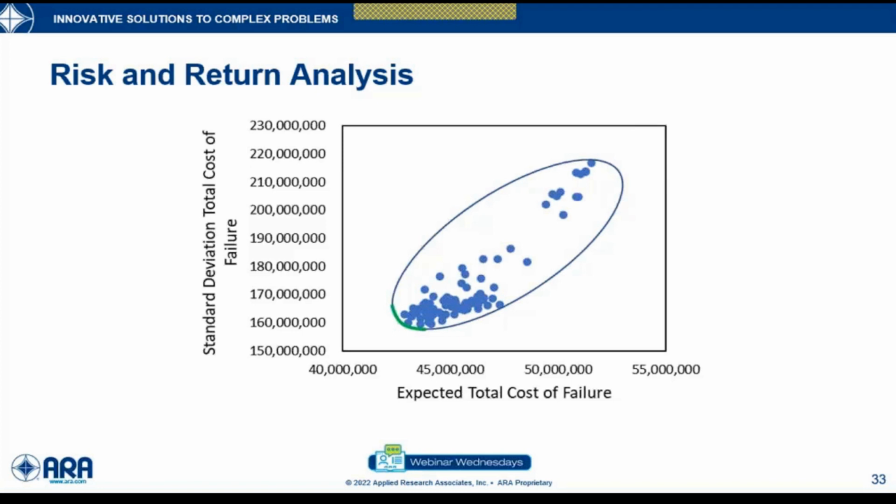The other thing to ask when we were talking about risk is basically the frequency of that event to occur. And the frequency in terms of probability, or basically, again, at the individual level, the probability of failure, or the frequency at the network level. So these are some of the basically major questions to ask. But when we're talking about risk-based data collection, focusing on the probability at the individual asset would be more critical, because you want to assess how probable is that asset to fail, given that we have observed 1 and 2 and 3, and should we go back and look at it.